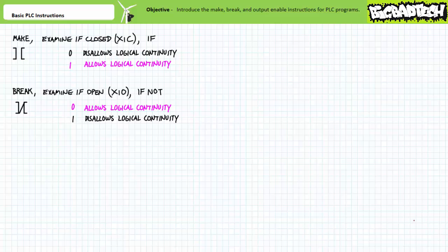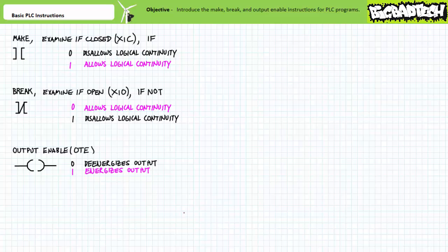Note I'm using the term logical continuity as if a PLC program really established or interrupted current to an output, but this is an analogy only. However, using the graphical ladder logic programming method, it's still very helpful to think of it in this manner. One can think of the left upright rail as a source of logical 1s, i.e. full control voltage. And to logically energize an output on the right, a rung must deliver a logical 1 from left to right.